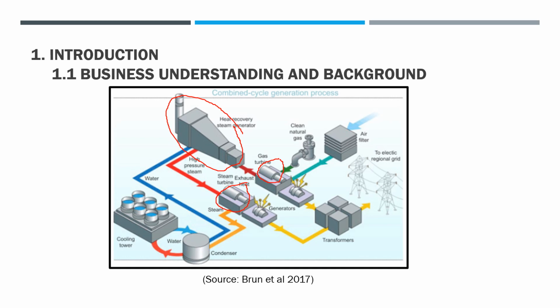Fuel burns at the gas turbine, makes the turbine blade spinning and driving electricity generator. The exhaust heat from gas turbine is captured by heat recovery steam generator. The heat recovery steam generator generates steam from this exhaust heat and delivers it to the steam turbine. The steam turbine uses this steam to generate additional electricity by driving an electricity generator.